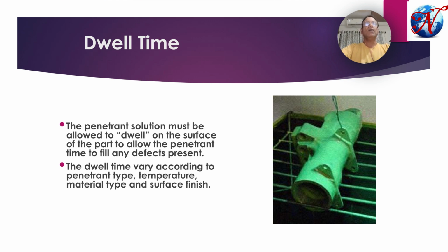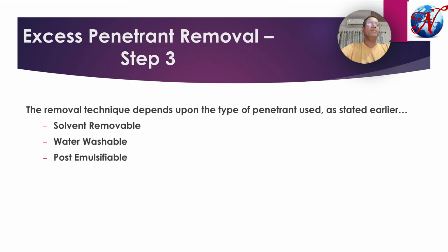So if the job part is in the range of 10 to 52 degrees centigrade, it will be 5 minutes. But if the temperature is more than 5 degrees but less than 10 degrees, the penetration dwell time will be double, that is 10 minutes. After the application of penetrant and the dwell time has elapsed,